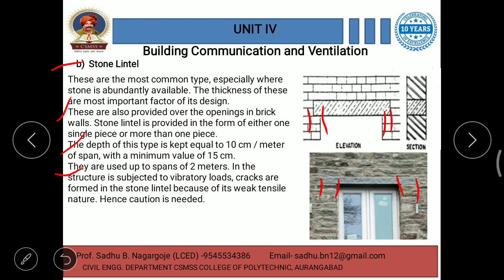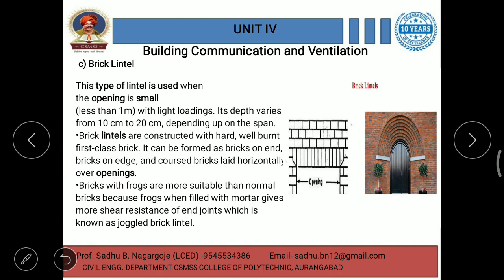They are used up to a span of 2 meters. If the structure is subjected to vibratory loads, cracks are formed in stone lintel because of its weak tensile nature. Hence, caution is needed. Okay, so this is about stone lintel.